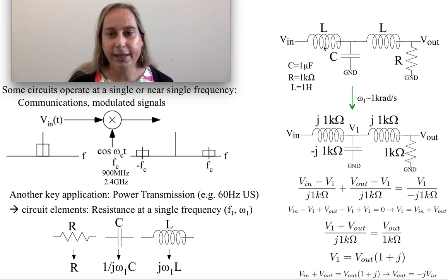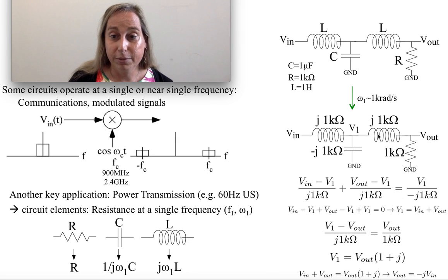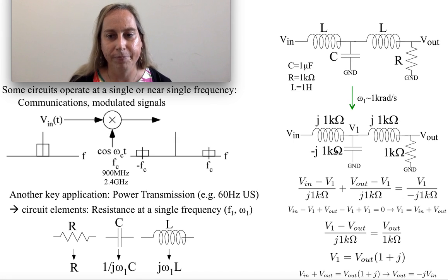And what you'd end up finding is that each of these inductors turn out to be an sL, right, or j omega L. And so it's j omega times that particular L. And this would give me 1 kilo ohm resistors times j. So they're imaginary resistances. And then the capacitance would give me something similar, and I'd say minus j times 1 kilo ohm.